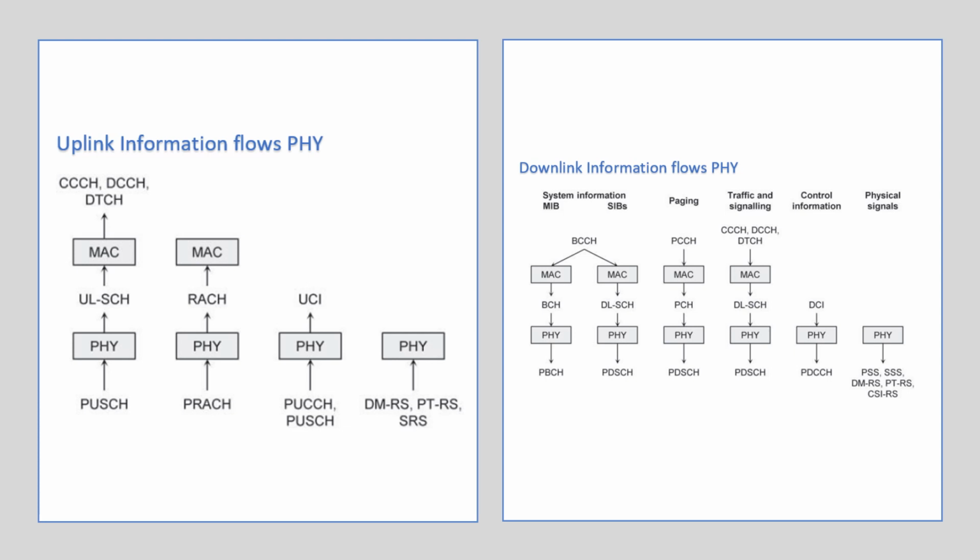A base station can send RRC signaling messages known as system information to all the mobiles in the cell, which describes how the cell is configured. At the highest level, that information is divided into two unequal parts. A base station can transmit a master information block, that is the MIB, which contains a few important parameters that the mobile needs to acquire a cell, and is delivered on a broadcast control channel. Now the broadcast channel and physical broadcast channel also transmit several system information blocks, numbered from SIB1 to SIB9. They are delivered first on the broadcast channel in the same way as the MIB, and then on the DL-SCH and PDSCH in the same way as the rest of the downlink signaling.